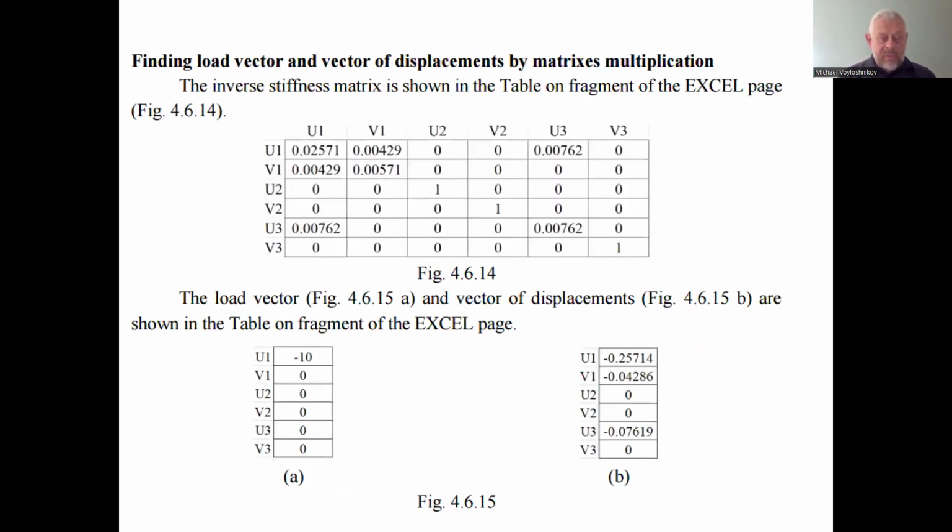To this matrix, we have to find the inverse matrix. We get the inverse matrix by the command available in Microsoft Excel. To find it, we select the place to insert the matrix, and we dial the command in the address bar of Excel. And we have the inverse of the stiffness matrix in the global coordinate system, considering the action of the supports, which do not allow the definite displacement in the abscissa or ordinate directions for definite nodes, the second or third node.